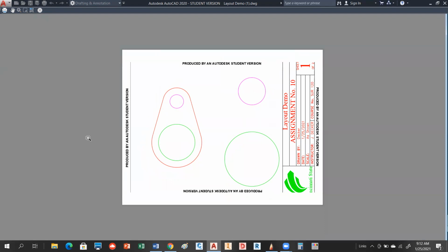But what you should notice here is that you don't have viewports. No viewport showing up here, no viewport showing up there, no viewport there. That's the ideal way of dealing with viewports, okay? If your viewports are showing up, then you either have them on the wrong layer or you've got that layer turned to a plottable layer. Now you can also freeze the viewports layer, and some people do that. I don't like to do that because I don't see my viewports while I'm working.